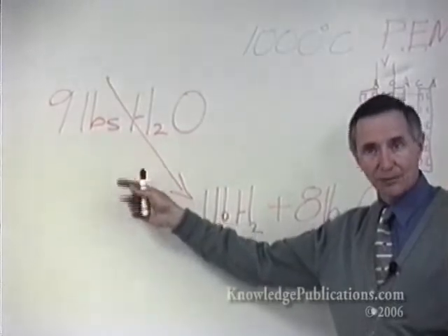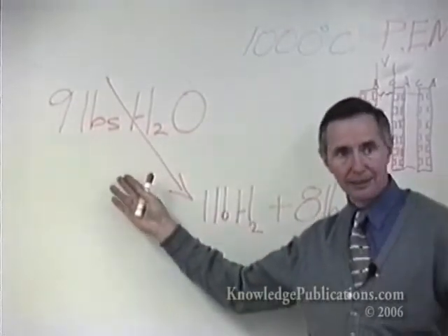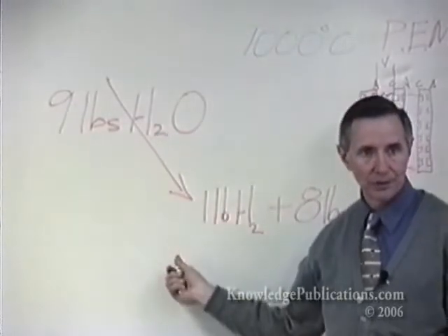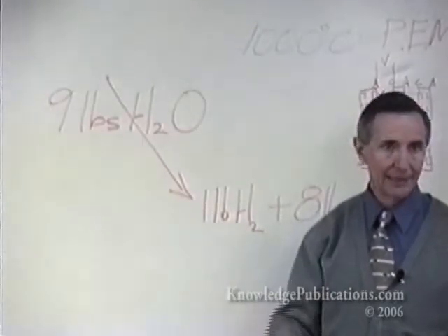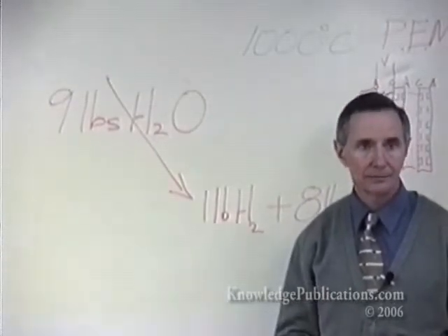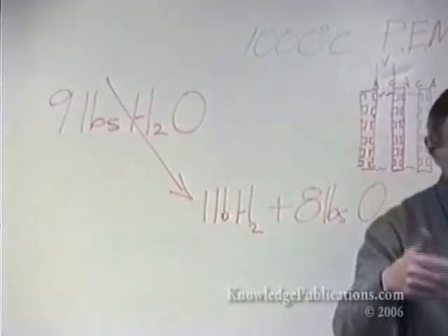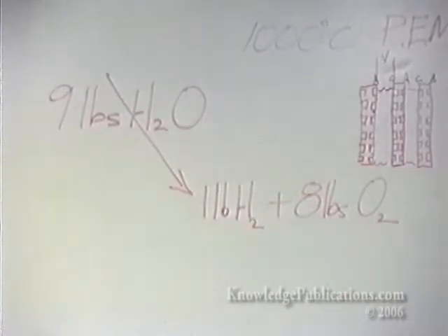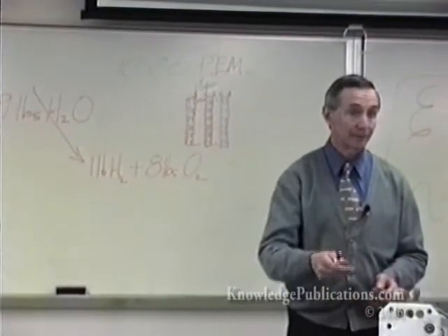Well, if you did have a fuel cell that was running at twice the efficiency of a heat engine, you could get enough BTUs out of the hydrogen produced by electrolysis of 1 gallon of water to run the same range as the gallon of gasoline. That's correct. By rule of thumb, and we absolutely admit that piston engines can be more efficient, but the way they've been running, they're about half the efficiency of fuel cells.